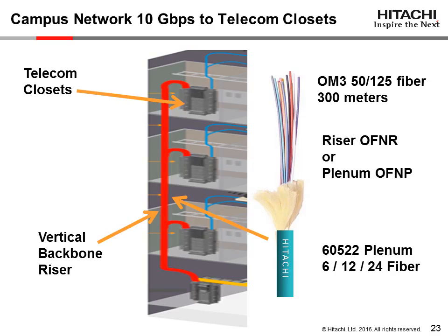The vertical backbone riser, by its very designation, is required to be riser rated. Hitachi has taken this one step further and offers plenum rated cables which surpass the riser flame requirement and have the versatility to be installed in either a riser designated area or an air handling plenum rated area. You should never mix riser and plenum rated cables in a building. Electrical inspectors generally want to see one type of cable present.